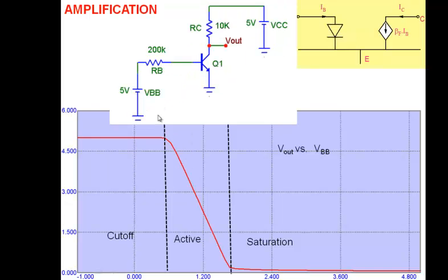This one here. So we said the moment you increase this voltage here, the transistor goes into active mode and you have a certain current IB. What is the collector voltage here? VCC minus ICRC, right? That's V out. What is the del V out by del V in? What will it be? VCC is constant. Del IC by del V in multiplied by RC. So you're saying the slope depends on RC here. The slope of this particular line depends on what RC I choose.